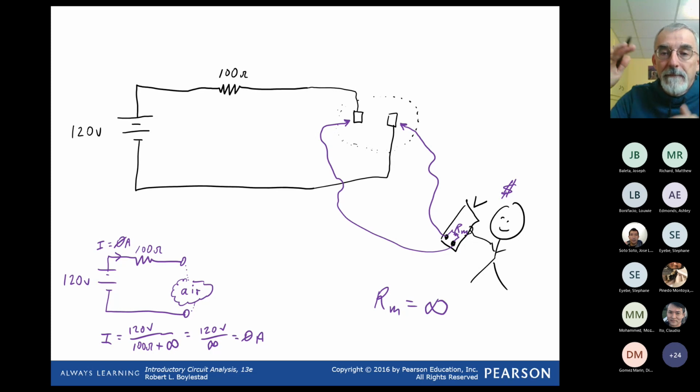Air is very high resistance. If it's a foggy St. John's day, the resistance could drop to a few mega ohms, and then we might see some sparks. Have you ever walked down the street and heard some little sparks coming from the power lines up above, especially on a humid day? Maybe the air resistance has dropped a little bit. But we tend to think of air as being infinite resistance, and when we divide by infinity, we end up with 0 current.